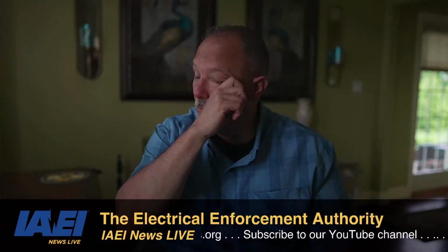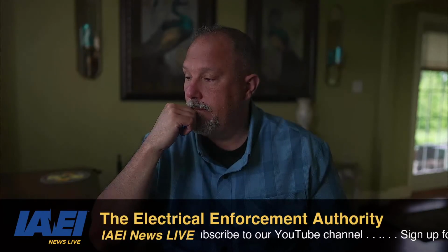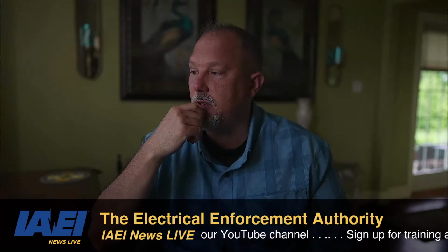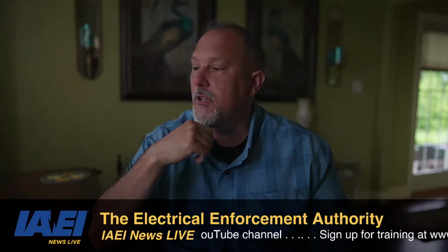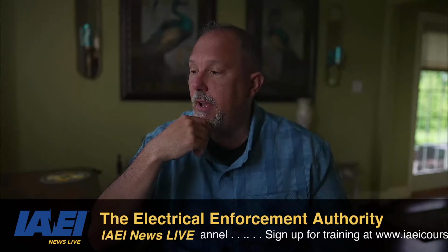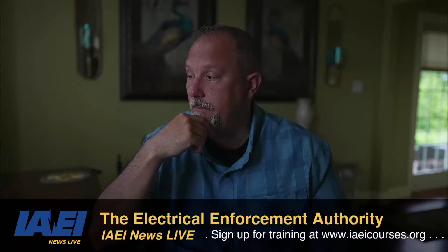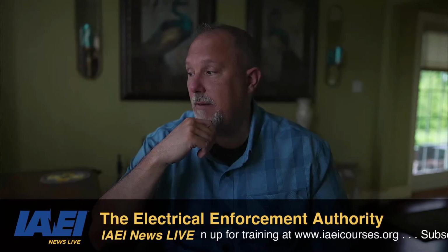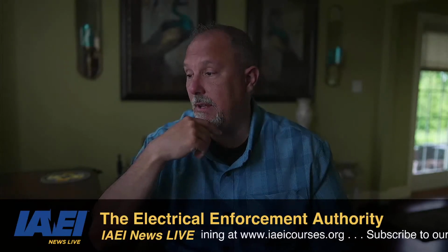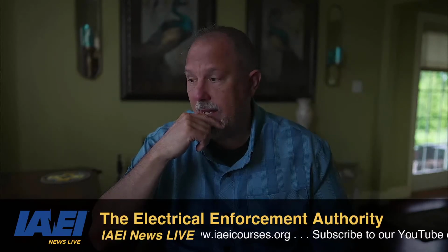Now let's look at the small appliances. Let's look at the small appliance in the kitchen, pantry, breakfast room, dining room, or similar area. The 2 or more small appliance branch circuits shall serve all wall and floor receptacle outlets covered by 210.52(A), all countertop outlets covered by 210.52(C), and receptacle outlets, exception 1 and exception 2.